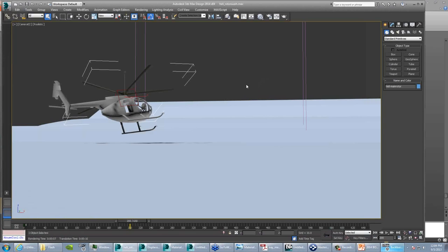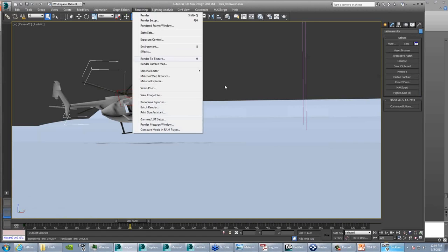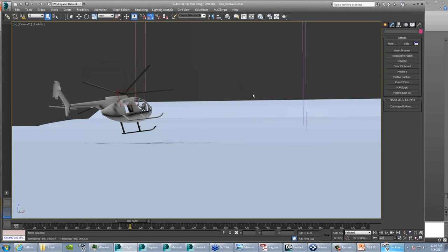When we do our panoramas, rather than using the 3D Studio Max panorama tool, we set up a camera that has a 90-degree field of view, and it's animated over 6 frames just to look in each of the different front, left, right directions. This gives us 2 things. One, we can distribute it over multiple machines because it's rendering an animation instead of a single image. And 2, we can do much higher resolutions than the panorama tool normally allows you to do.